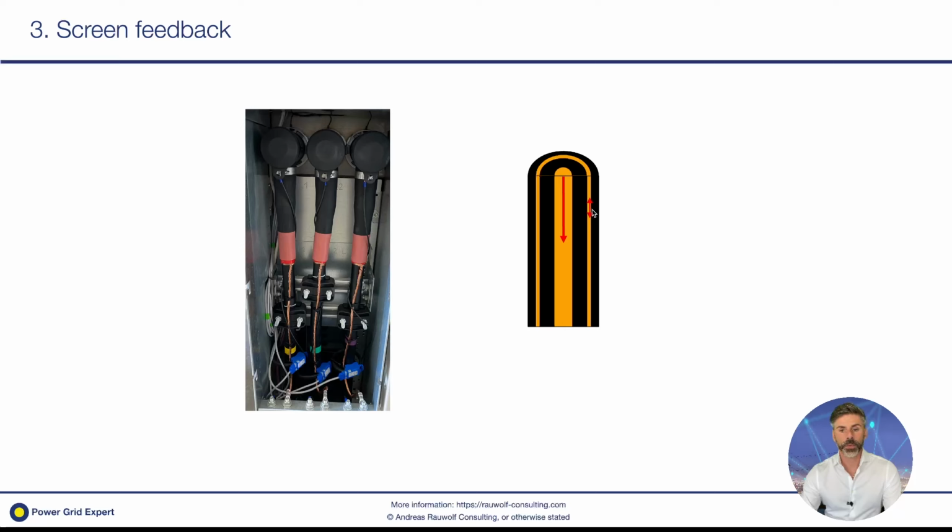There are different currents in different directions flowing depending on the situation in the network, depending on the installation. This is what we don't want to measure, and this is what we don't want to see. So if we install the CT around the cable, we will measure the vectorial sum of both these currents, but we only want to have the core current.